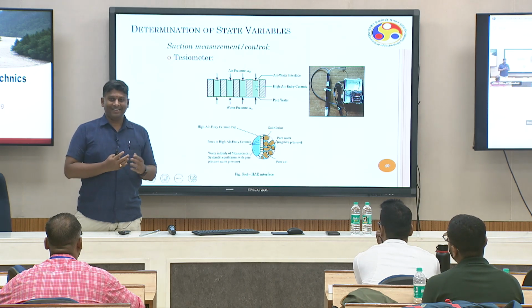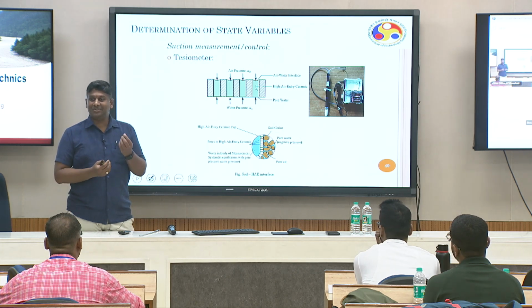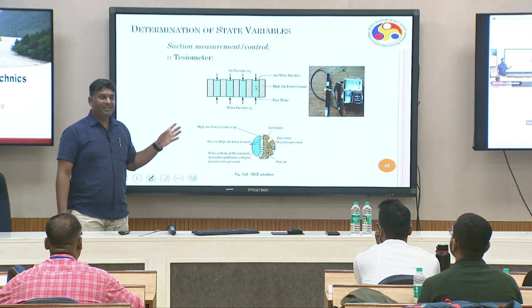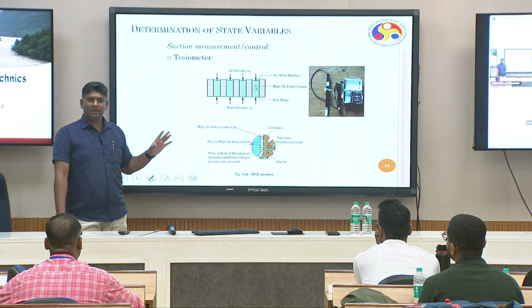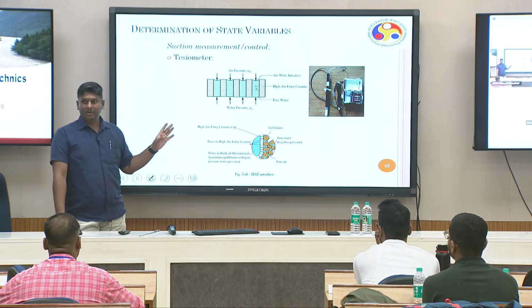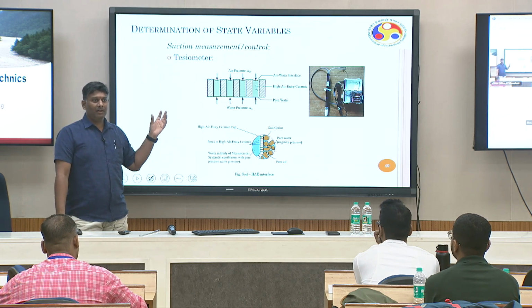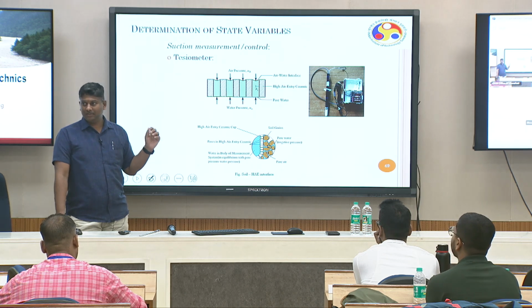As Bhargav was asking in the previous class, can we design something, small pipes, etc.? This itself is very tough. But soils have much higher suction, with thinner, finer pores than the ceramic disc we can design. Maximum capacity is 15 bar. That's it. Beyond that, I haven't seen. Commercially available air entry discs have a maximum capacity of 15 bar, 1500 kilopascal.